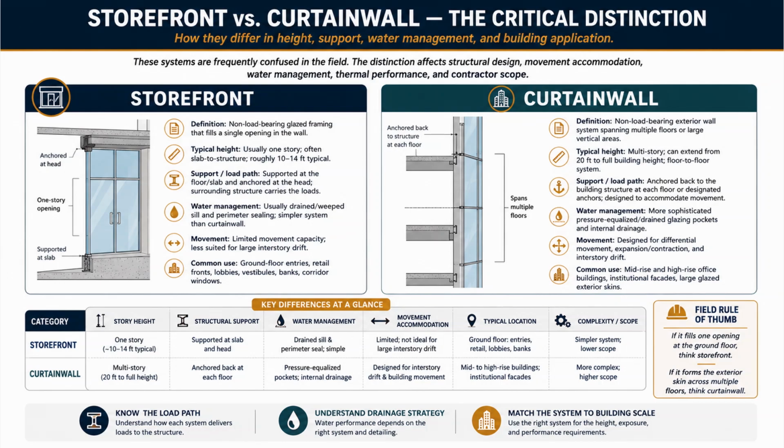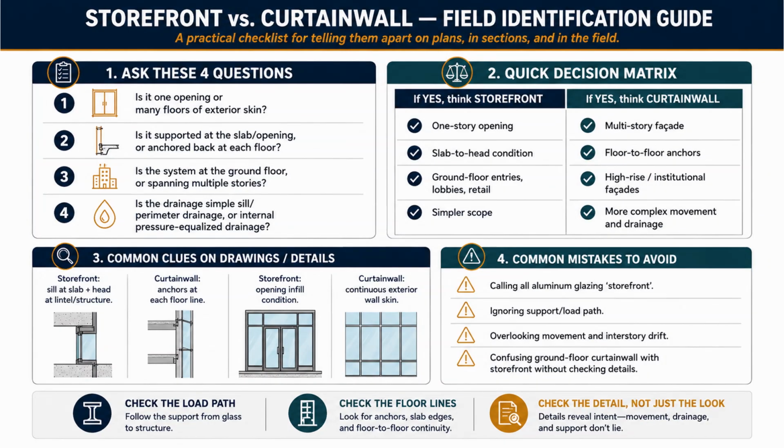The 3 takeaways. Know the load path, how each system delivers loads to the structure. Understand the drainage strategy. Water performance depends on the right system and detailing, and match the system to the building scale. Let's lock in the distinction with this field identification guide.